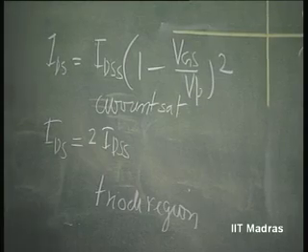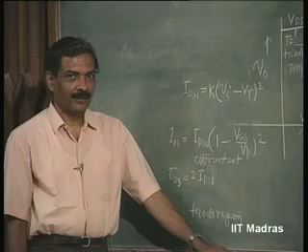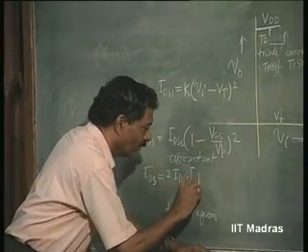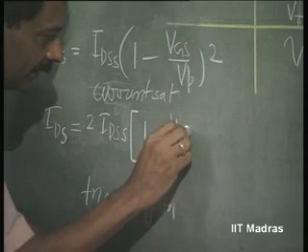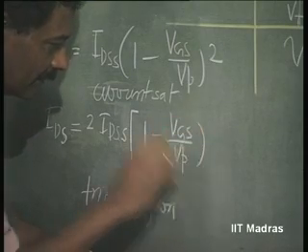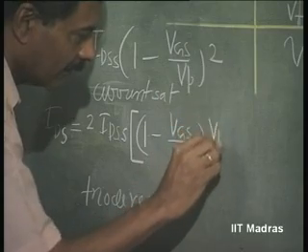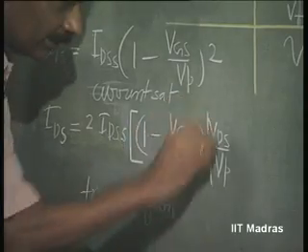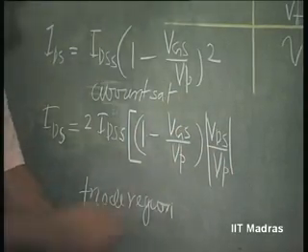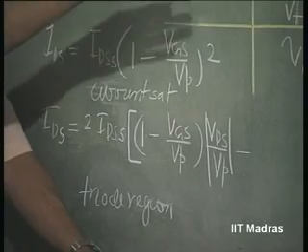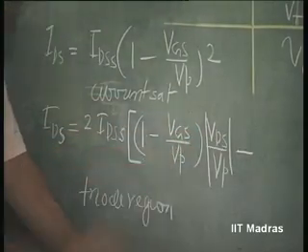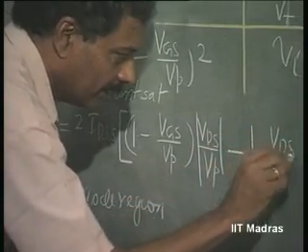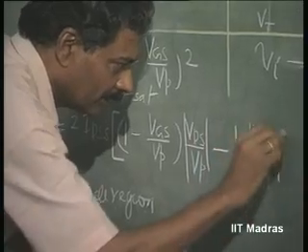It is going to be similar, mathematically it is similar, into 1 minus VGS by Vp into, now VDS and Vp are opposite signs. So, we put for the magnitude of current this, because we have known the current direction. Magnitude of current only we are interested in, half of VDS by Vp.